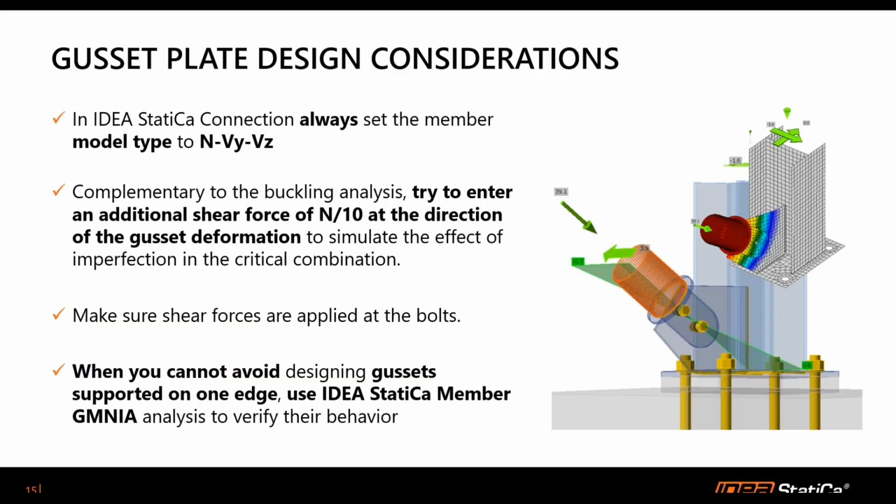So that was it. And before we close, let's revisit some of our gusset plate design considerations in IDEA StatiCa. When you're using IDEA StatiCa Connection and you have a bracing that's connected to the gusset plate, always set the member model type to N-Vy-Vz. As we have demonstrated, this has a significant influence on the buckling behavior of the member.